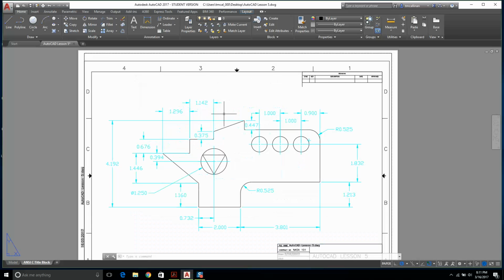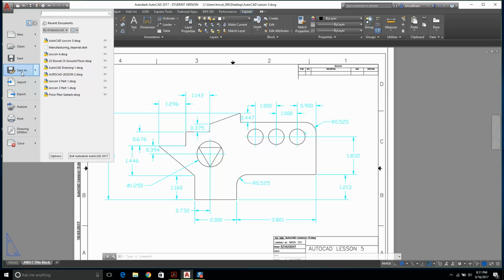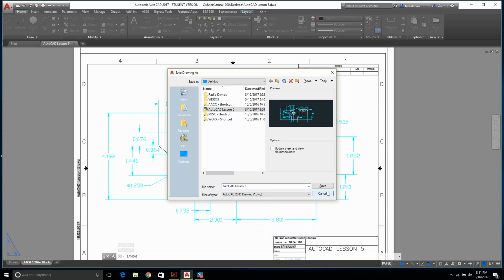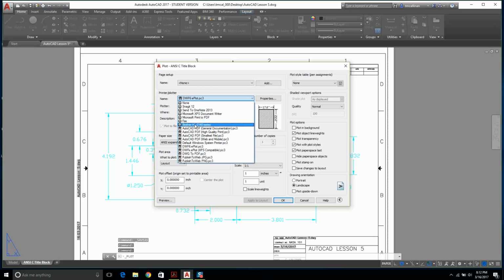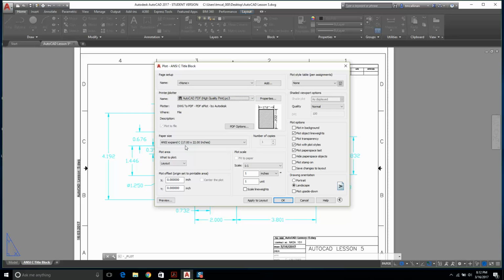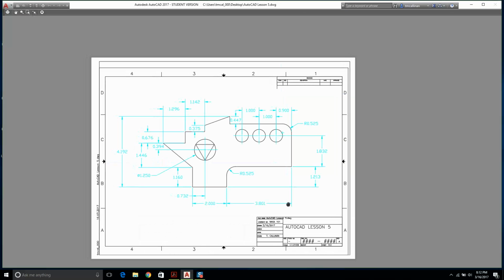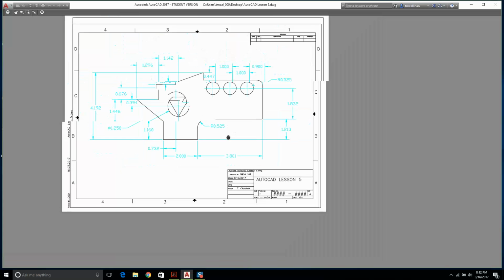Okay, I like that. So what are we going to do? We're going to go save as PDF. You save it as a PDF? Nope. Print. Microsoft Print to PDF. AutoCAD PDF. High quality print. Extents. Centered the plot. Fit to paper. 17 by 22 is a size C. Look at that. Lovely job. Excuse me. Yeah, I like that. So that's decent enough. Alright.